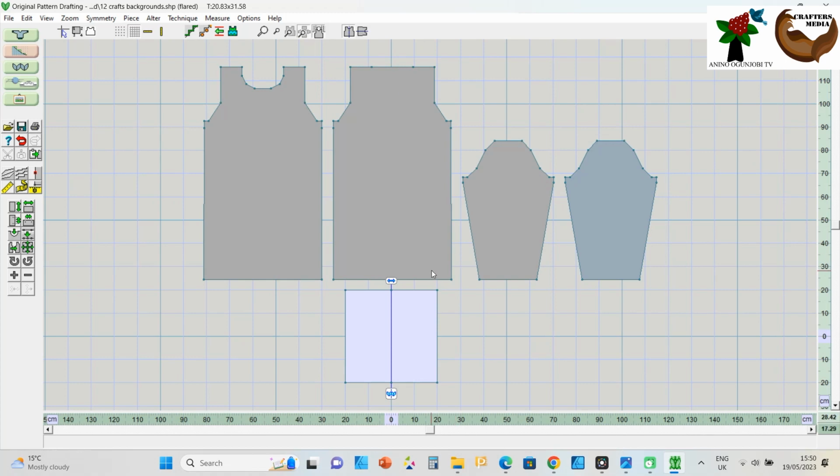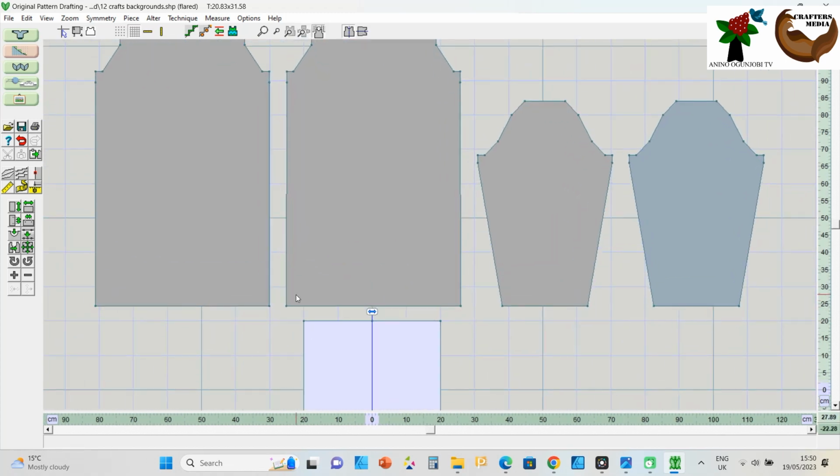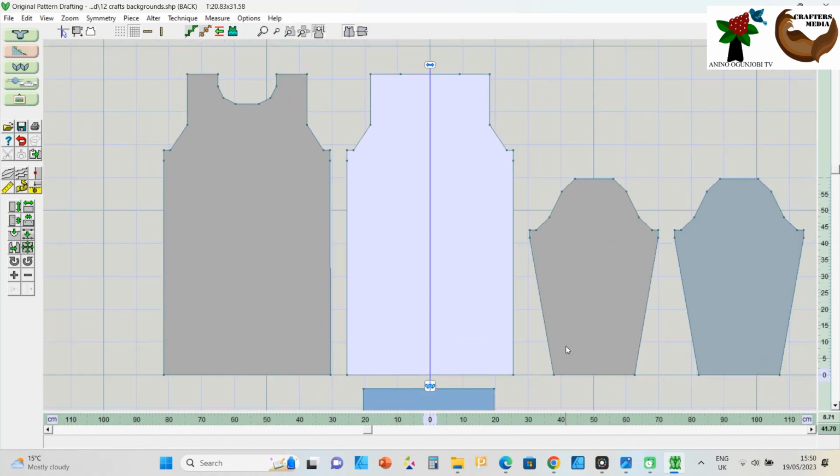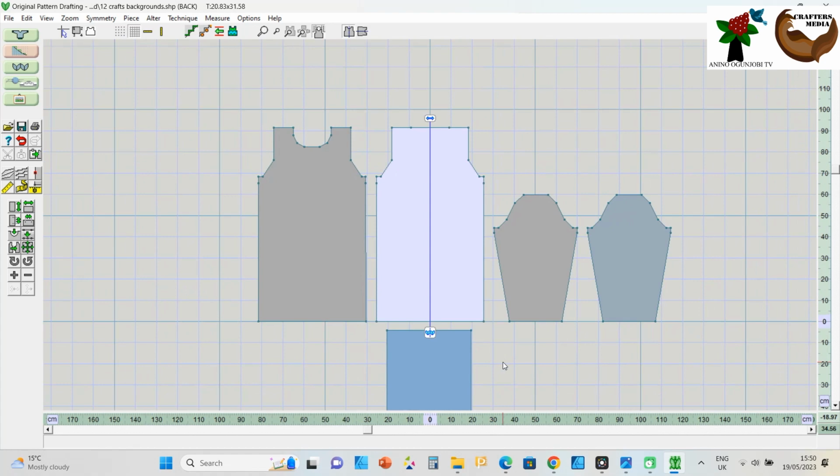But one thing you need to do before you make a flared piece is to measure the garment. So taking our ruler, let's measure a straight line. I'm going to click on this node here on the back side of the garment, or the front side, just the base node, and I'm going to measure it to. I need to activate the one I'm going to measure first. Just click on it and it's highlighted white.